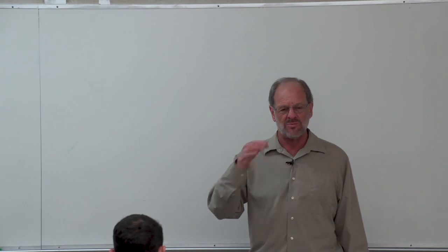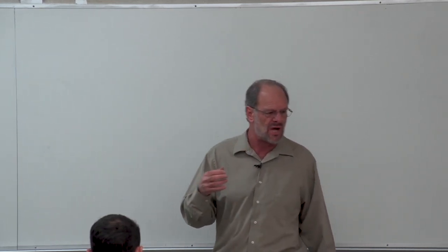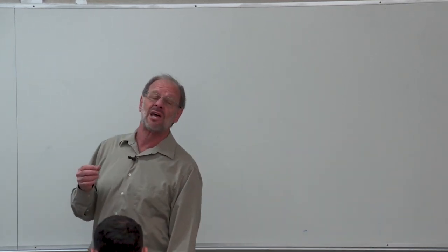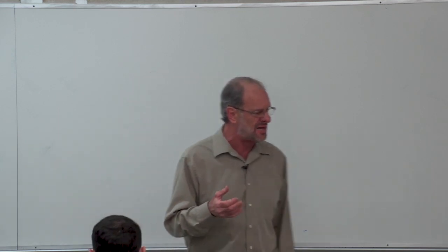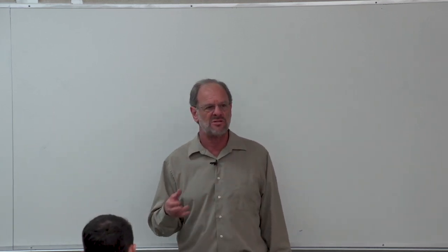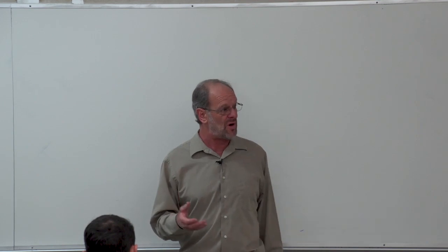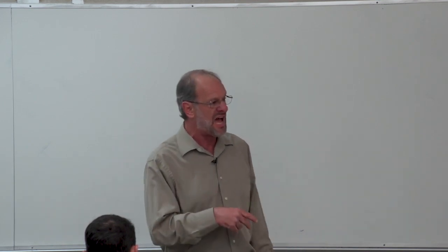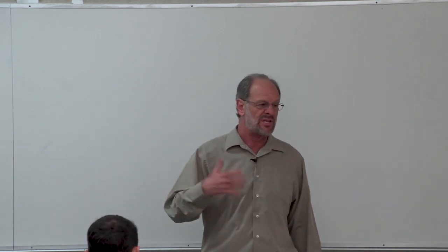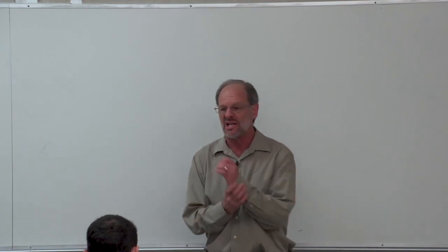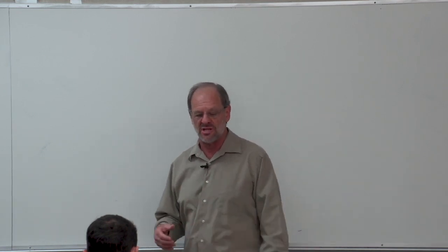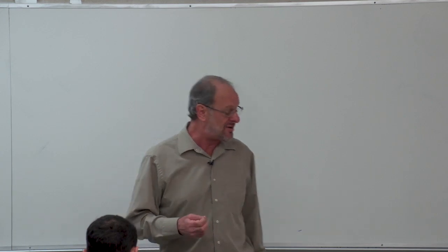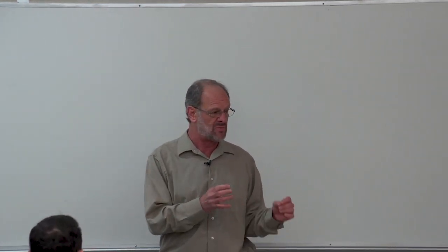Others dealt with problems involving flow. For instance, there were some problems with an ideal gas compressor that used air, and I guess the last one was an ideal gas turbine that used air. Those are important review problems, not because we need it now, but because we need it next week. When we deal with the Brayton cycle, we're certainly going to be dealing with air compressors and air turbines, and we need to understand how to use ideal gas with constant as well as with variable specific heats.